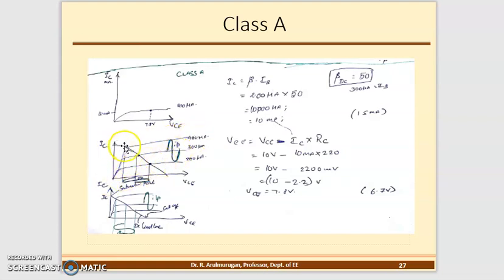Then next, you draw the load line. How to draw the load line? The load line is connected between the saturation point and the cutoff point. It is connected between the saturation point and the cutoff point.